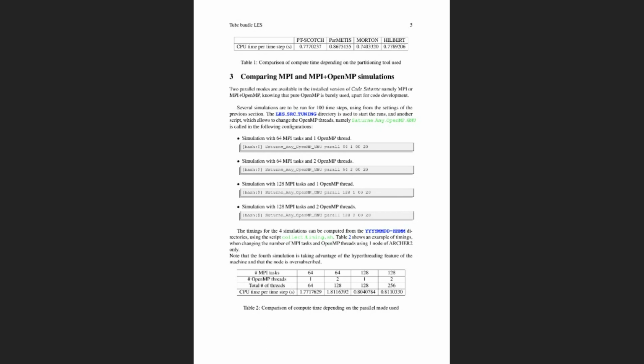You have to be sure that you configure your test case for the size of the files you are going to dump on or read from the disk, and this depends on the file system, basically. For instance, for Lustre, you can add some striping, and this really helps. You can multiply the writing and reading speed on the disk by 2 to 5 sometimes, depending on the size of the mesh. So that was just a short explanation of what should be done there.